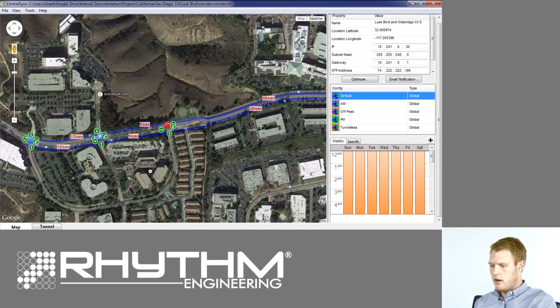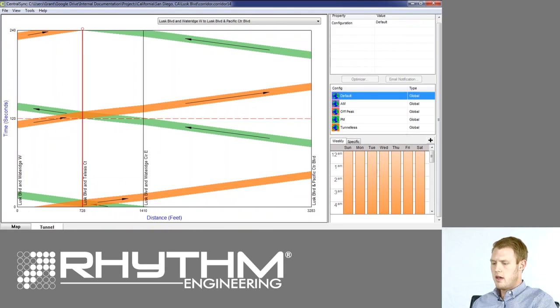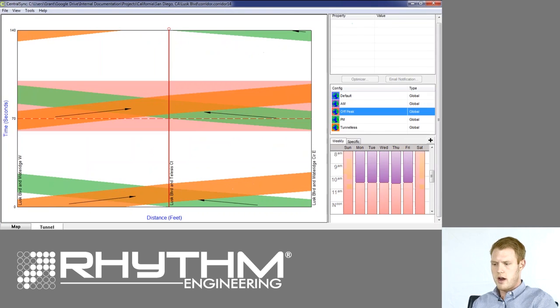Now the next screen I'm going to show you is the tunnel tab, and you access that from the bottom tab right next to the map tab. Once you've clicked on that, it brings you up a time-space diagram with time on the vertical axis and space on the horizontal axis. So for example, if I select the off-peak configuration, you'll see that InSync displays a time-space diagram of the off-peak configuration.